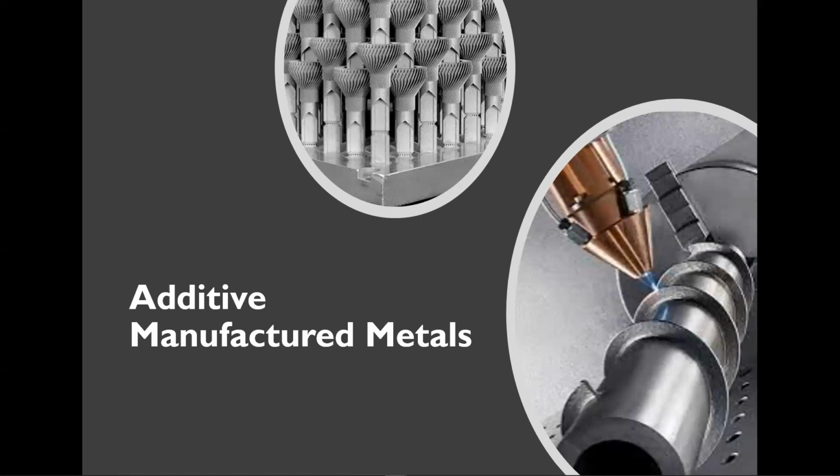And the PVD coating, or the physical vapor deposition coating, will allow us to create the coat by attacking the 3D printed material, or substrate, with the sample or the metal to be coated, using that vacuum chamber as mentioned before, or the sputtering chamber. And by controlling the deposition factors, such as the deposition rate, we can thus control these intrinsic stress effects in the material.